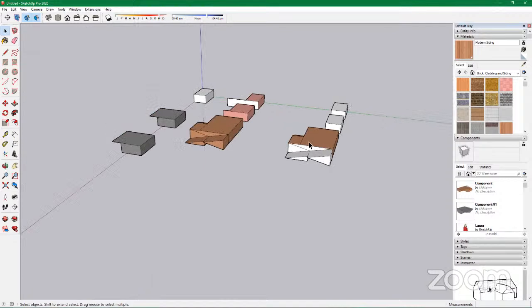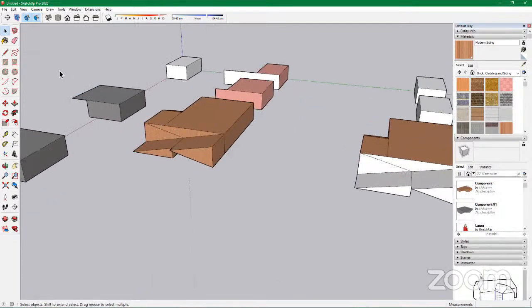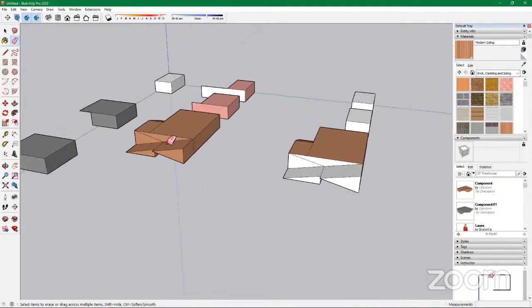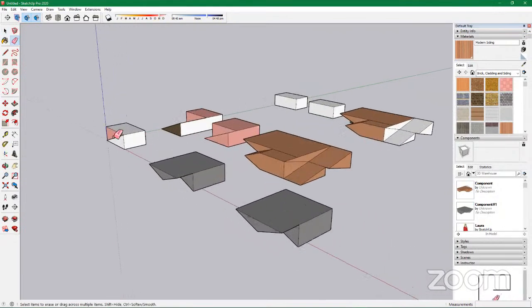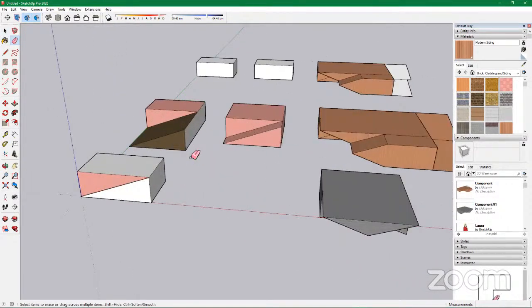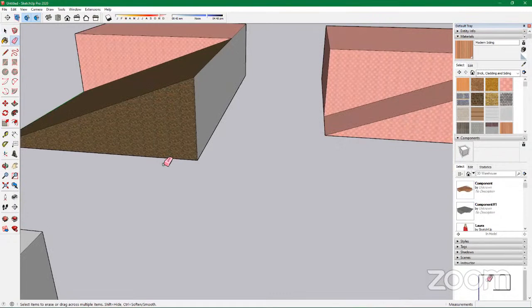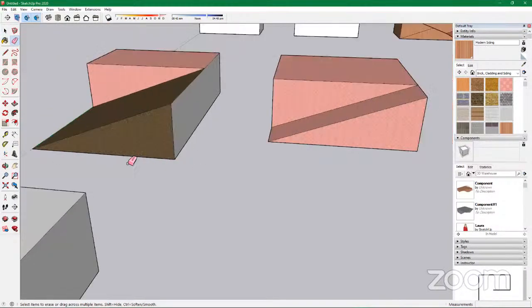Okay. So now, let's get over to the next one. The next one we're talking about is the eraser tool. With the eraser tool, yeah, you can actually erase entities. You can erase your models. You can erase lines and all. So in this case, I want to erase this line. Note that erasing this line means that I'm taking off this face because there will be no connection between these 2 points to create a face. So I'm just going to erase this line and the line will be gone.